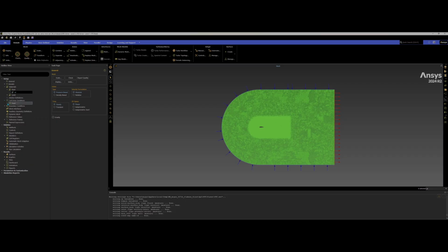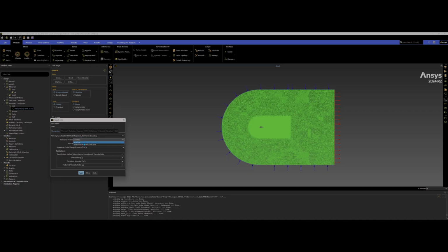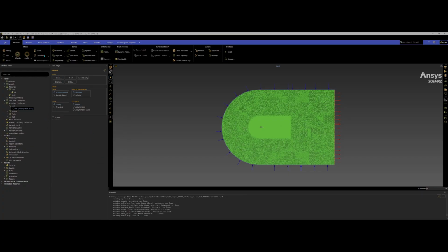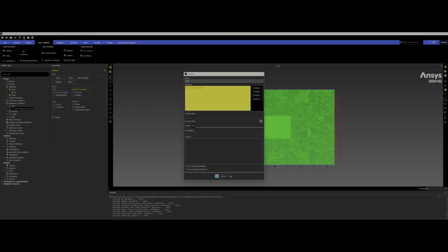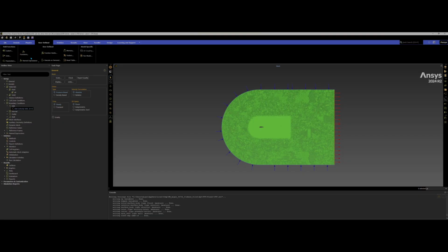Now, of course, make sure it's all good. Everything's all great. Now, boundary conditions, inlet. Most people, what they do is that if they go here in inlet, let's say, put in components, and then they'll make a new parameter right here. However, I have a better way of doing that, instead of having to individually calculate each velocity component, and this is something I came up with myself, I found out by myself. Just do named expressions, and then set one for degrees. I'll do -3, so we're going to start from -3 to 15, and set this as an input parameter. And there you go.